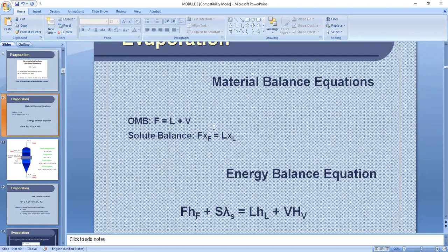I think in the industry, you know already that the evaporator water, if it's being recycled in the boiler, should have zero solids present in it. If not, your boiler will explode. So that's how important it is that your evaporator unit should not have any entrainment.